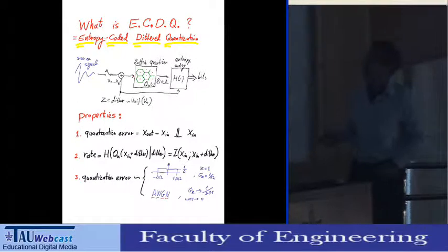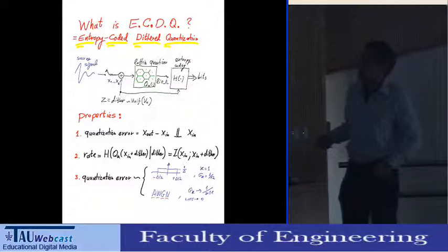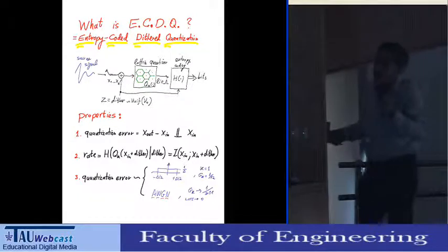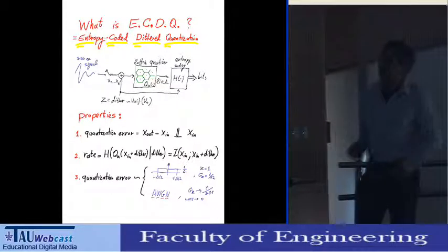So before that, what is ECDQ? I mentioned entropy coded dithered quantization. In general, ECDQ means that I'm taking a discrete-time source. I want to do vector quantization using a lattice quantizer, but before that, I'm dithering. I'm adding intentional noise before quantization, and after, in the reconstruction, I will subtract this noise again. So it's not a real noise; it's a pseudo-random noise. And I'm also doing entropy coding based on knowing the dither. So again, this is a known quantity.